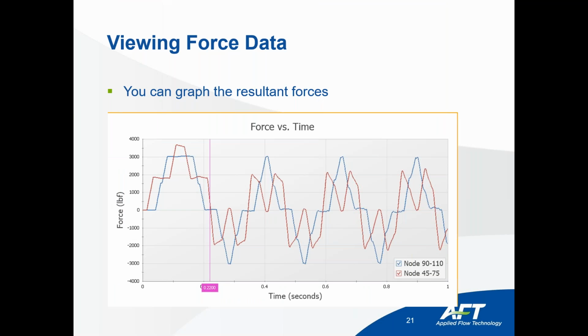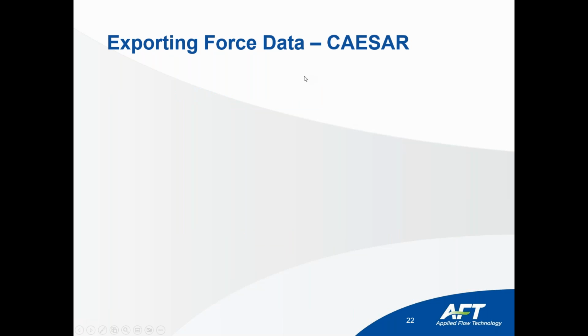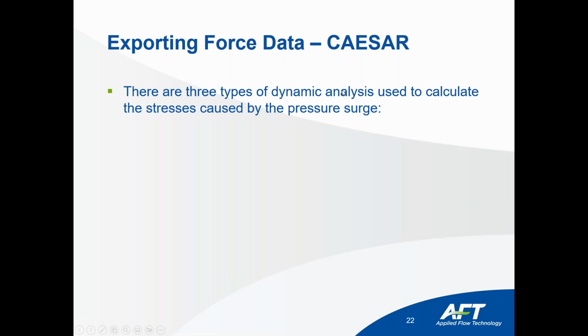We're ready to export to a pipe stress program because, as we indicated, B31.3 talks about a level of stress, or allowable level of stress. So we want to see if we comply with code. As I mentioned, we're going to export to Caesar.